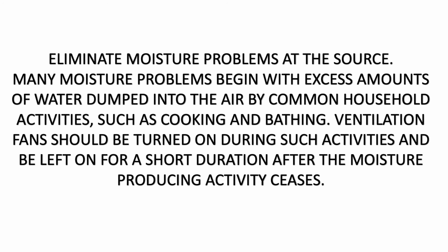Eliminate moisture problems at the source. Any moisture problems begin with excess amounts of water dumped into the air by common household activities, such as cooking and bathing. Ventilation fans should be turned on during such activities and be left on for a short duration after the moisture-producing activities cease.